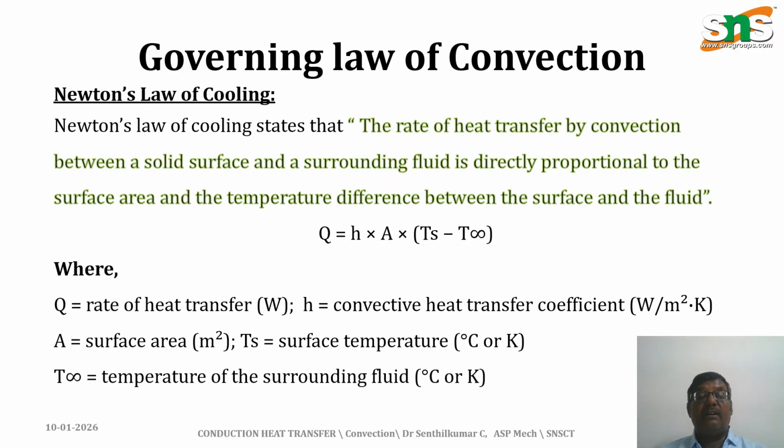We already saw the governing law for conduction, which was Fourier's law of heat conduction. Here, for convection, it is Newton's law of cooling. Newton's law of cooling states that the rate of heat transfer by convection between a solid surface and the surrounding fluid is directly proportional to the surface area and the temperature difference between the surface and the fluid. So the equation is Q equals h A delta T.